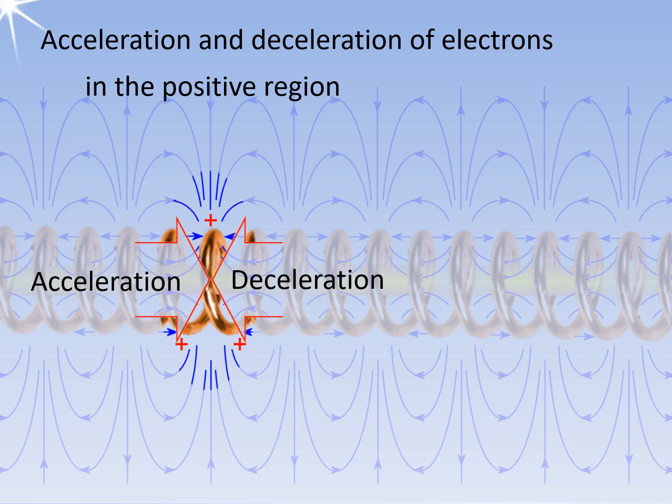This local electric field has a relatively large influence on the electrons due to the inverse square law. It is superimposed on the voltage potential from the collector, which is still distant. The axial electric field components accelerate some electrons and decelerate others. The increase in electron charge ahead of the region and decrease behind the region produces an electron bunch.